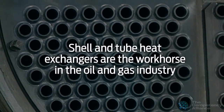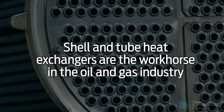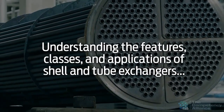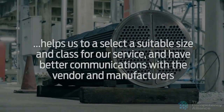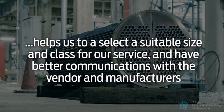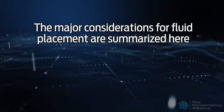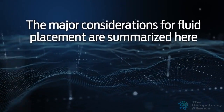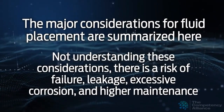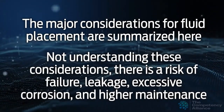Shell and tube heat exchangers are the workhorse in the oil and gas industry in terms of heat exchangers. Understanding the features, classes, and applications of shell and tube exchangers helps us to select a suitable size and class for our service and have better communications with the vendor and manufacturers. The major considerations for fluid placement are summarized here. Not understanding these considerations, there is a risk of failure, leakage, excessive corrosion, and higher maintenance.